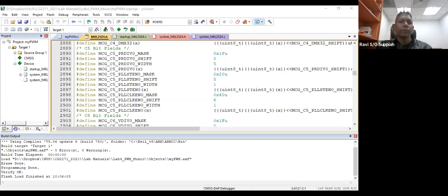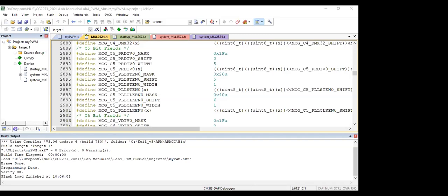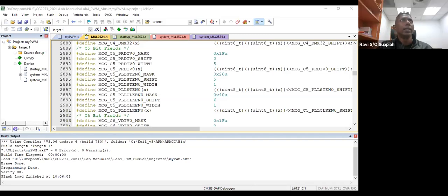So there are different development platforms for the same controller, and if you use them, maybe you have different types of masks and header files. I see, so the software aspect will vary depending on which platform you use, but the hardware is consistent, so the data sheet is consistent. So even if you don't have any of these masks, you can still program it using your own mask, using your own bit masking techniques.